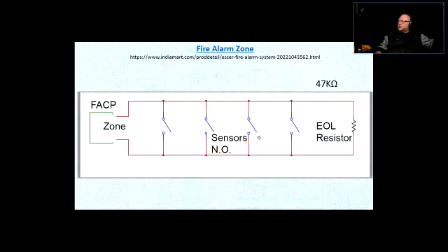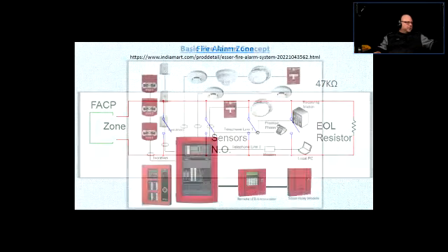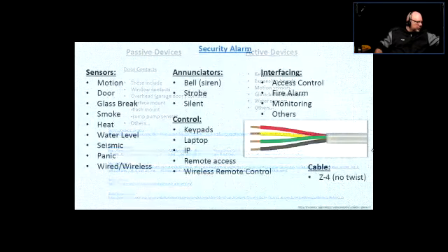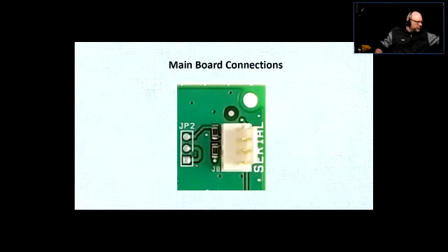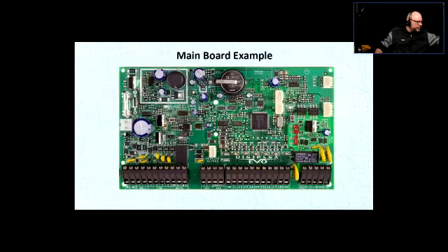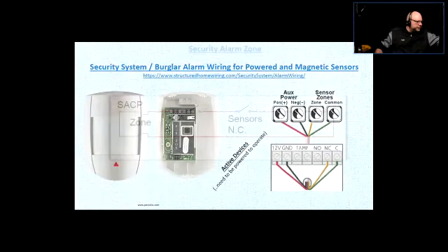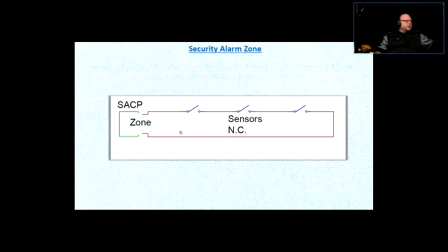Remember when I showed you the security alarm? Let me go and find it. There you go. Remember, in a security alarm, the zone looks for a closed loop. So the devices would be connected in series. As soon as one opens, then the whole thing triggers.